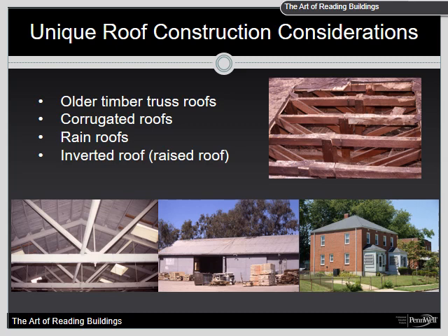Older timber truss roofs are not always arch-shaped. They can also be flat or gabled. Timber truss roofs offer significantly more durability during fires than lightweight truss. Factors such as aging, multiple roofing layers, alterations, higher fire loads, and longer burn times are more responsible for timber truss collapses than the actual truss design itself.